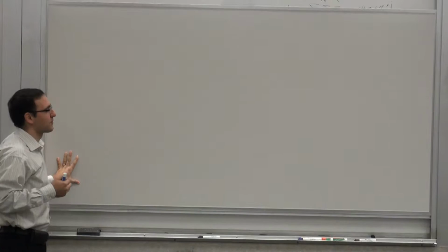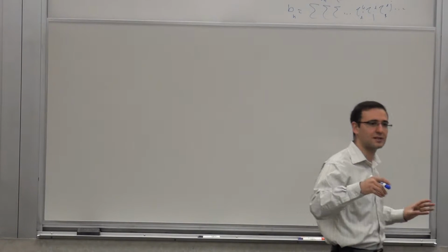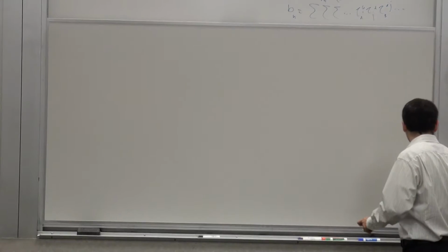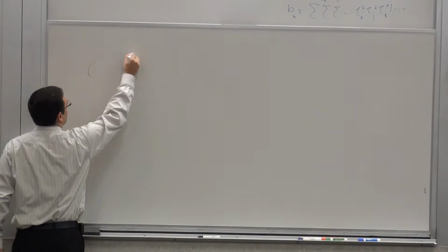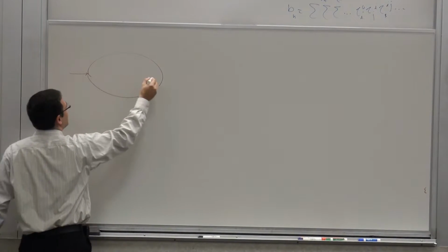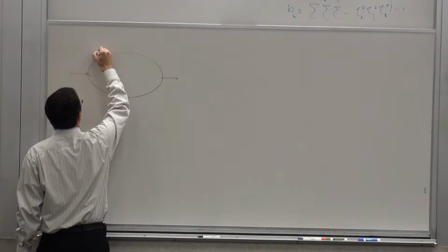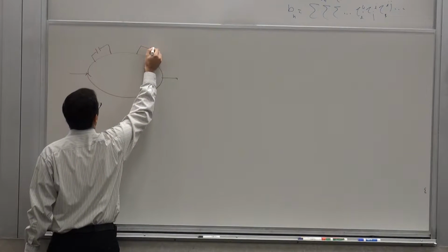But okay, how do we arrive at these? Well, I'll take a little detour here. We'll go and do the second order system, which we could directly do as this B2 and A2, and that would subsume the second order system. But I think it's better to do the second order system because in that context you get more of a feel for it. So in a second order system, let's say there are just two capacitors for now, and then you can see how it generalizes. It's very simple to generalize to inductors.